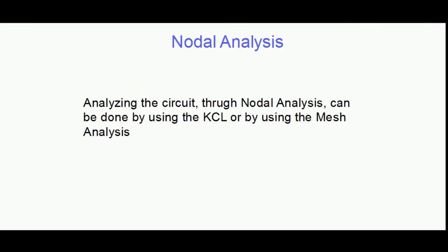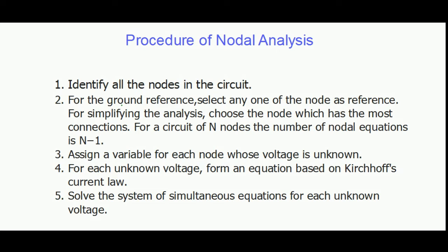Now coming to the procedure of nodal analysis. First of all, identify the nodes of the circuit. Second step, take any node as a reference. For calculation simplification, we take a node having more connections as the reference. So at the end, if we have n nodes in a circuit, we get n-1 nodal equations.